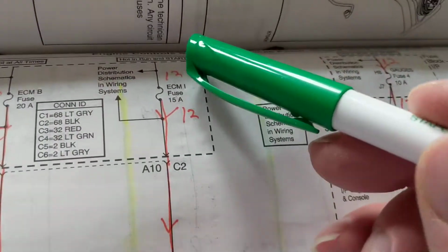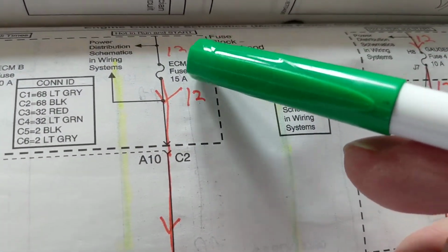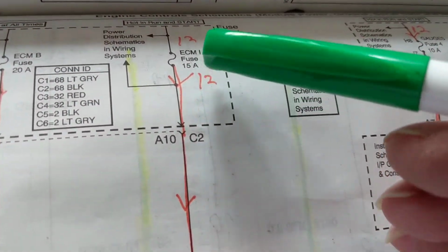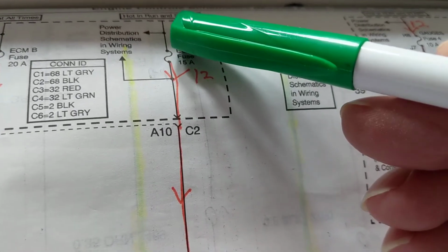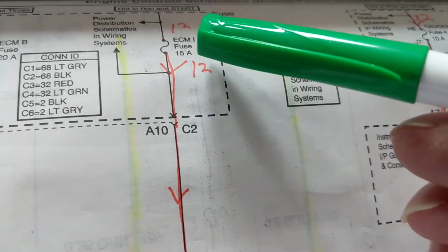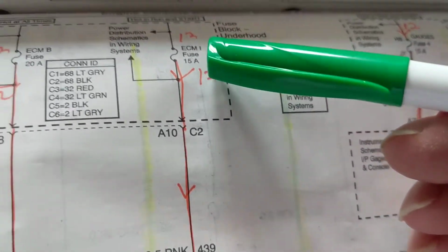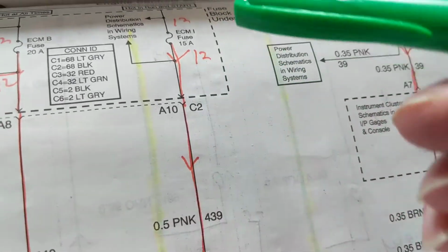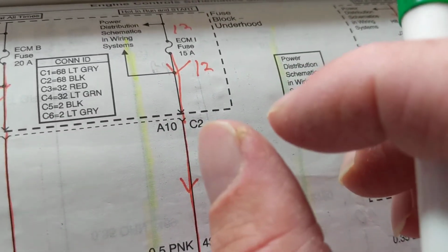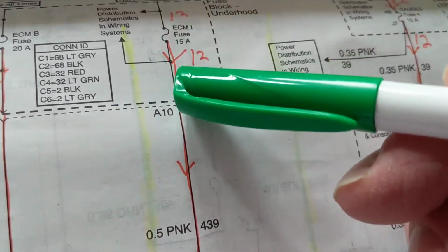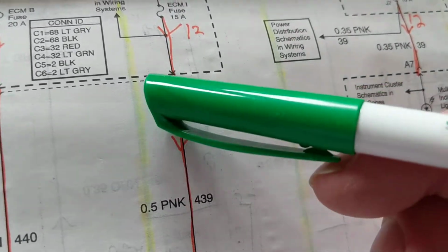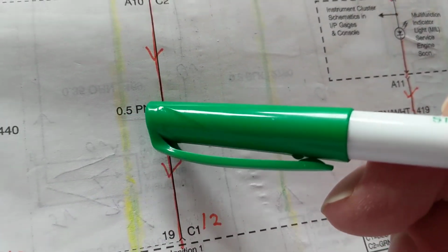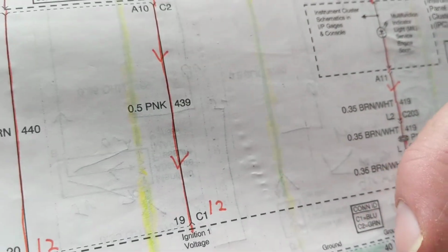But before that, we have a battery. We go through a fuse, ECM1. Whenever you're looking for the computer fuse, look for ECM or PCM. That right away tells you. It goes through a fuse and current will flow and come out the other side. Only 15 amps, remember. Doesn't take too much current. When you see blower motors or things like that, sometimes they're 30 amps. So ECM is a very small fuse, a mini fuse. The current goes in and comes out of C2, which is the connector, terminal 810, a pink wire. Pink 0.5 is the gauge. So you're going to be looking for a small wire.